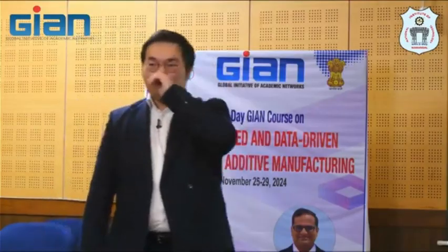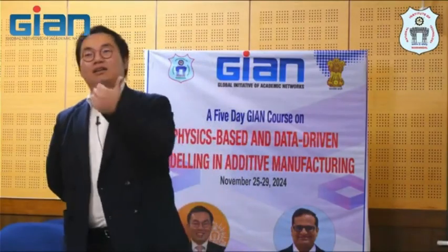But CM247LC or Inconel 718, they have preferred segregation. As you know, we have also done that. There is preferred segregation. There is formation of gamma double prime also in the as-printed state. In which material? IN718. Yes, of course, we see it from casting and from additive. But it's a total surprise that you don't see the formation of gamma prime.